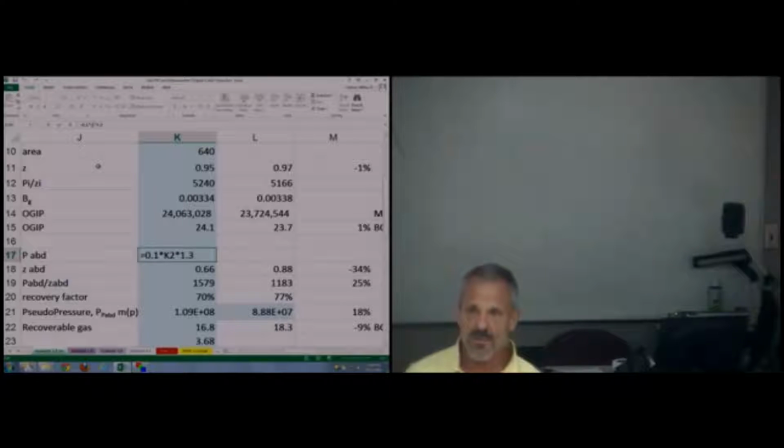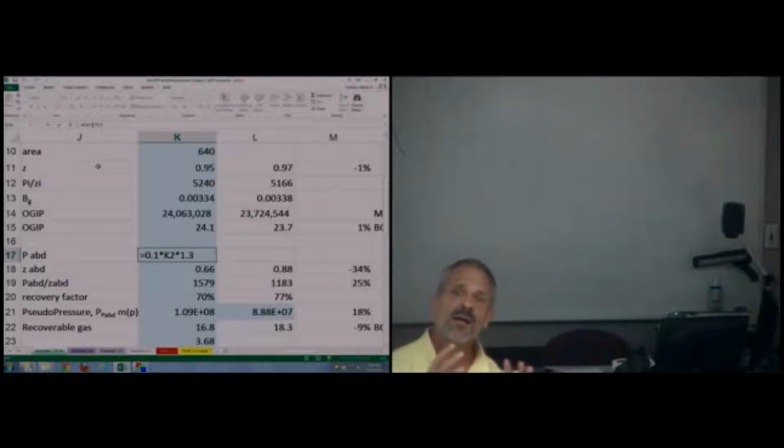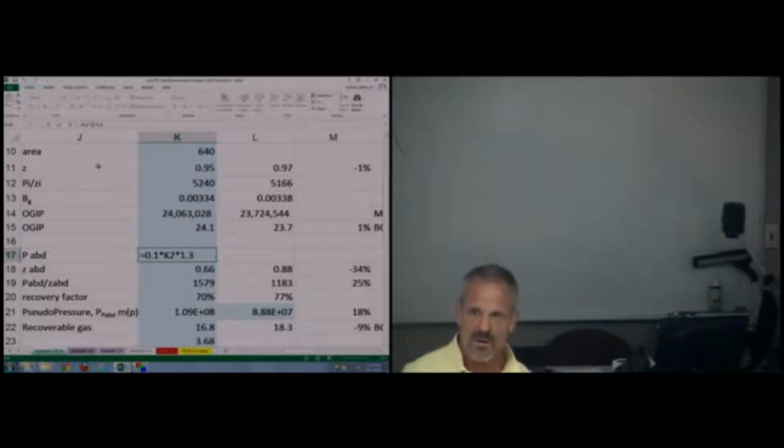Because that well stream gas gravity is what's in the reservoir. So when I'm calculating Z to get my formation volume factor, when I'm calculating viscosity, when I'm calculating pseudo pressure, anything I'm calculating, I want the composition, the gravity and impurities of the reservoir gas, not of the primary first stage separator gas, even though that's what I'm selling.